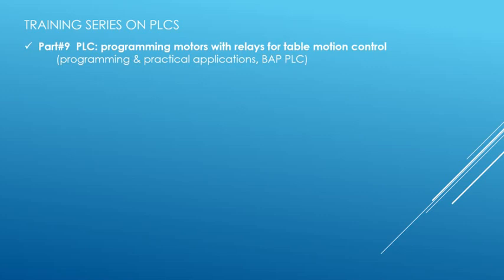In most cases, if it's a small motor, first you connect the relay with the PLC, and the PLC is controlling the relay. The relay is controlling the motor, if it is a small motor, DC or AC, single phase. However, if you have a three-phase motor, usually you connect the relays with the PLC, and that relay will be connected to a contactor. The contactor will be controlling the motor, especially if it is a three-phase or high horsepower motor. It is better to use a contactor.